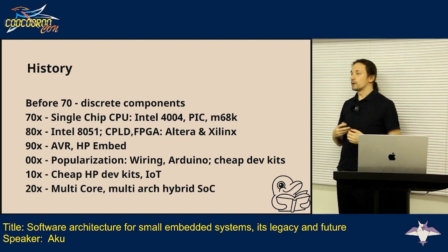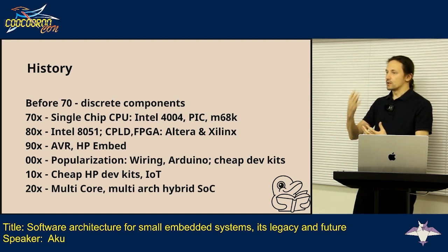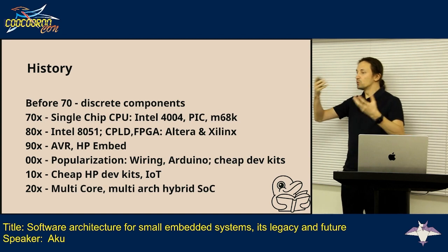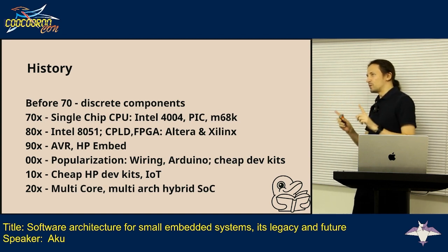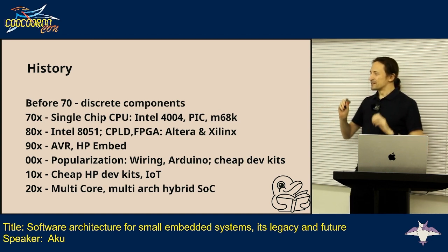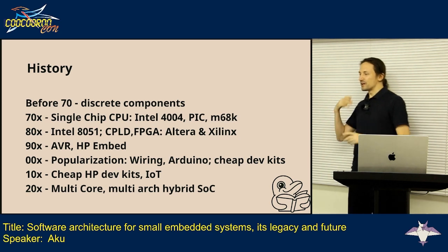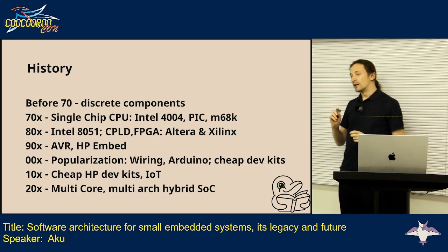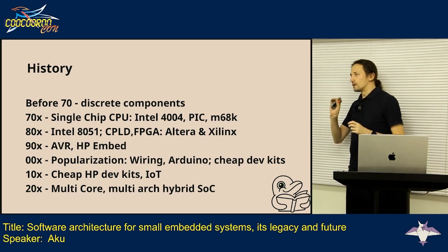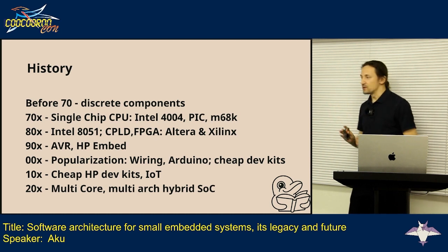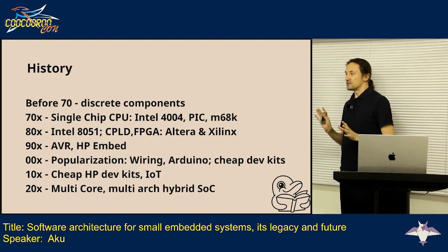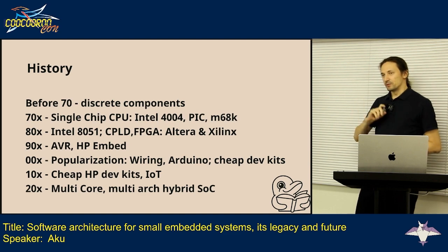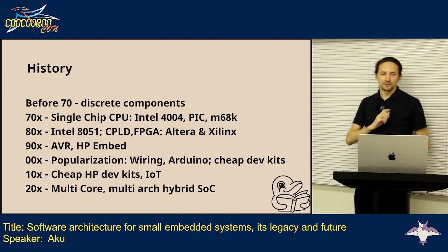They even combine RISC cores with ARM cores, with multiple cores, like one die with 6 cores. Some of them are low power, some of them are for high-performance processing, and some of them are for designing new peripheral buses. Let's say we want to design something that does not yet exist in silicon. You will be able to do that with those blocks.